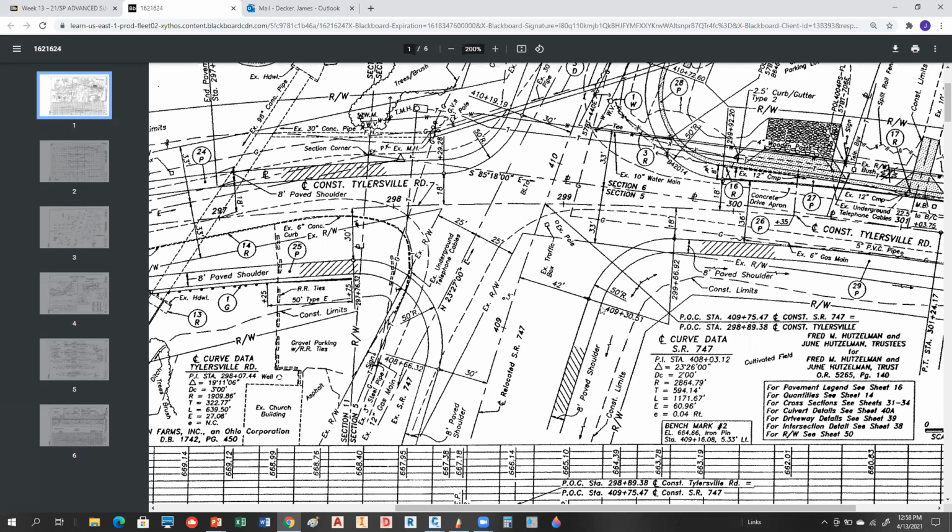So that's the station for where this curve PC is, if you will. And this 299+66.92 station is referenced to Tylersville. So these stations are actually referenced to two different center lines. Notice they also have two different offsets. You have a 42-foot offset here and an 18-foot offset to that, but the radius itself is 50. So that's just a simple curve.